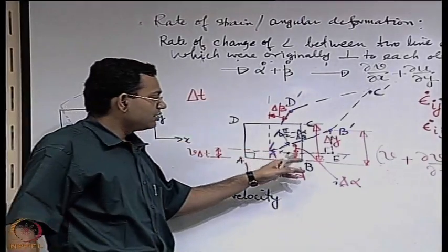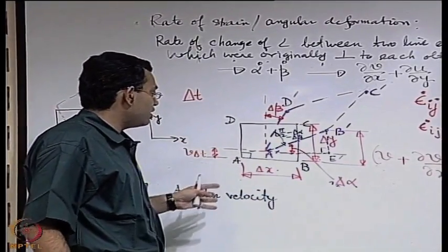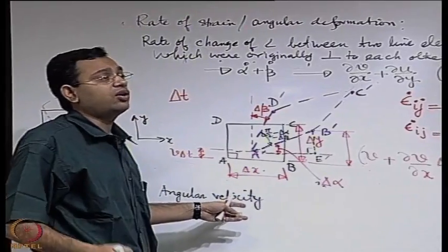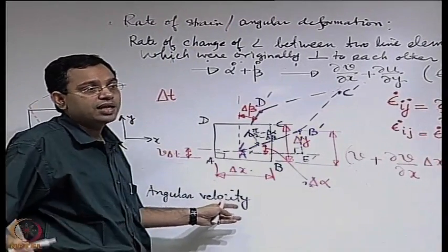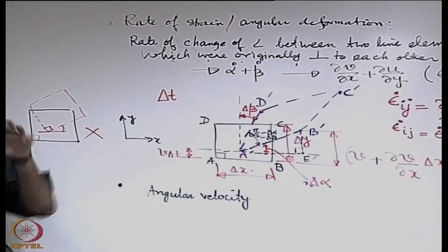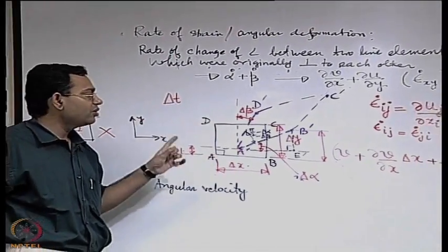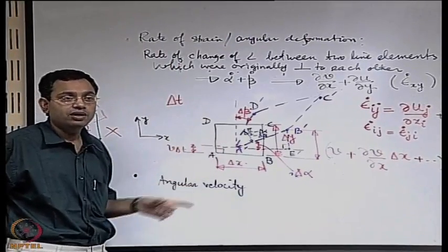Here those angles are different, and therefore we have to come to our angular velocity definition with a compromise, not exactly the same as we do for rigid body mechanics, but keeping in mind that in the special case that it becomes a rigid body, it should follow the rigid body mechanics definition of angular velocity.